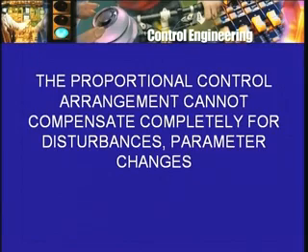So, what I am saying is, if the load torque changes, of course I am not going to measure the load torque, that is an assumption that I am making. If the load torque changes and I am not going to measure anything else other than the speed, and my arrangement is as before, the comparator, amplified through Ka, etc., no change. So, my reference voltage of 21.15 volts produces 1500 rpm for a load torque of say 30 Newton meters, no problem there, or it could be 20 volts because for the tachogenerator we have taken only a part of its voltage.